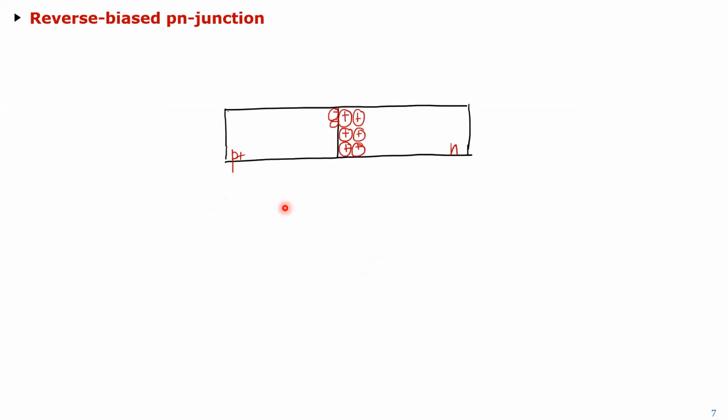The PN junction which is important to us from a VLSI perspective is the reverse bias junction. You have 10 million transistors, you have 20 million reverse bias junctions. So that's worth spending time understanding what it is. I think we've already talked about it a few times. I'll again give you an idea on what happens during reverse bias.